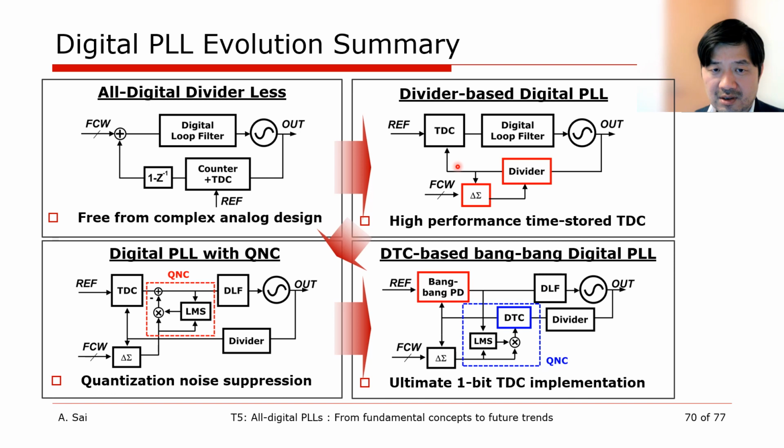In addition, not only do they solve the problem of the divider quantization noise by QNC, but also with the introduction of the DTC and the bang-bang phase detector, researchers have taken digital PLL to almost the extreme level.